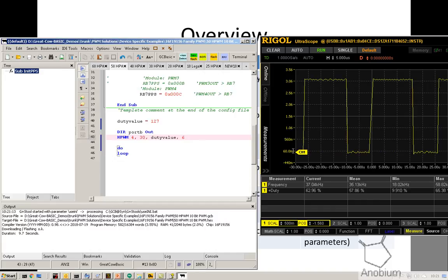So here we've said it's a 30%. I've set it to a duty of 60, which is puzzling my little brain here. I've got a minimum here. What have I got on my scope up here? A duty of 60%. That's because it's taken it as a word.